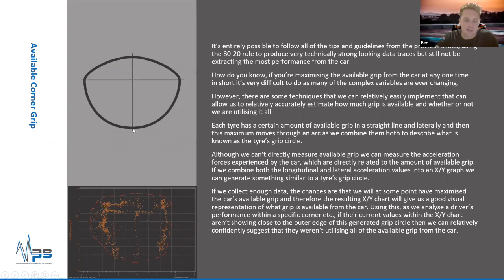So this would be braking in a straight line, and this would be purely steering. Then if we do a combination of brake and steer, as talked about in the trail phase, we get this arc, this sort of circle shape. That's the amount of grip essentially a tyre has available. We can map grip to acceleration, longitudinal and lateral acceleration, and equate acceleration to grip.